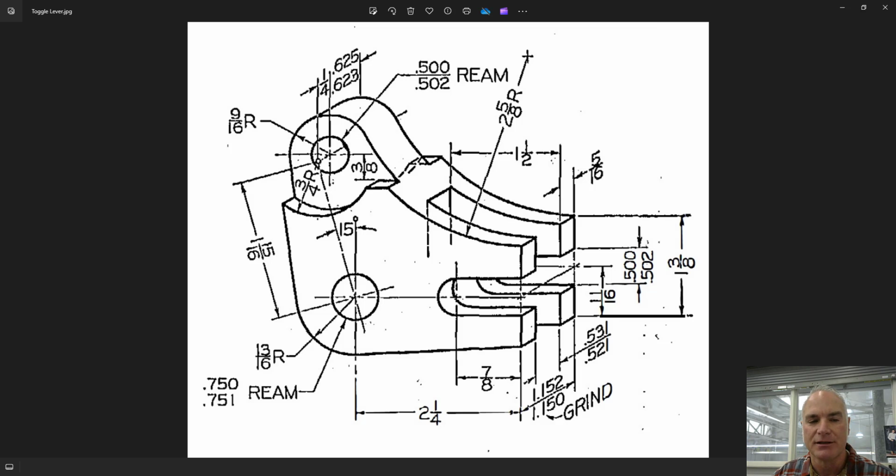Autodesk Inventor has several methods for tolerancing, with the most common being symmetric, deviation, and stacked limits. Each method has unique applications. For example, let's consider a simple mechanical part, a shaft with a diameter of 25 millimeters. The drawing might specify a dimensional tolerance as follows: 25 millimeters plus or minus 0.1 millimeter. This means that the acceptable range of diameters for the shaft is from 24.9 millimeters to 25.1 millimeters. Any shaft diameter within this range is considered acceptable and will function correctly within the assembly.